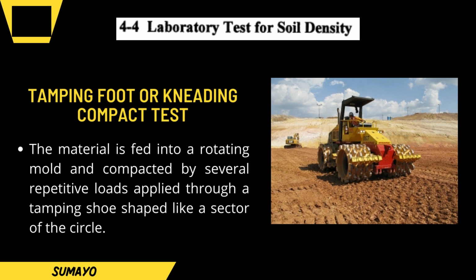Tamping foot or kneading compaction test. The material is fed into a rotating mold and compacted by several repetitive loads applied through a tamping shoe shaped like a sector of a circle. About 25% of the specimen is covered in each application. Compaction is through kneading action, in contrast with the static pressure or impact test.